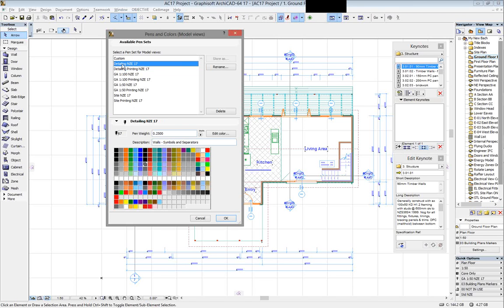Now the biggest problem we have with customers is that they say, I only use 8 pen weights, so they go and change the first 8 pens to their custom pen weights. This is something we used to do way back in ArchiCAD 9, but since ArchiCAD 10 it definitely hasn't been the case. So if you were to change these to, for example, 0.1 and 0.13 and 0.15 and 2 and 3 and 4, changing the weights of these, the problem is then...